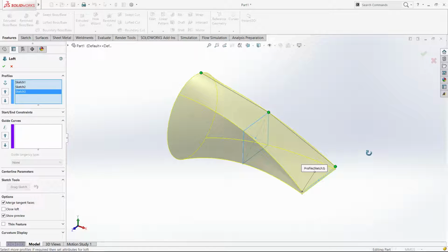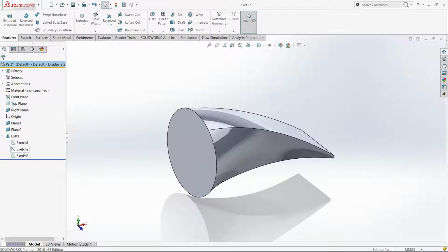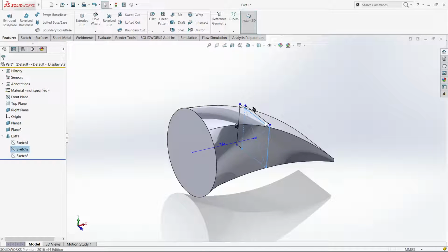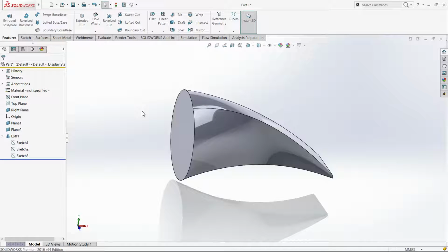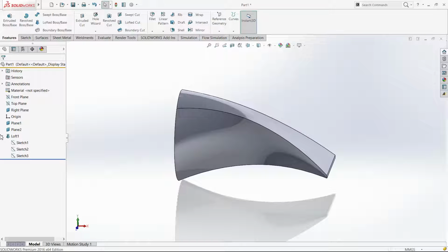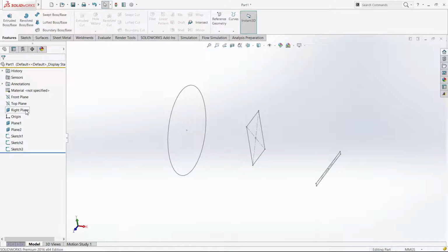So you sort of see the intent of this shape right here. If you go OK, you can see what happens. Inside this Loft feature, you can change these dimensions and it will update automatically. And that's the result that you have. Now, that's one way of doing it, and we're also, well, let's just delete this feature, say yes, and we'll keep the other profiles.